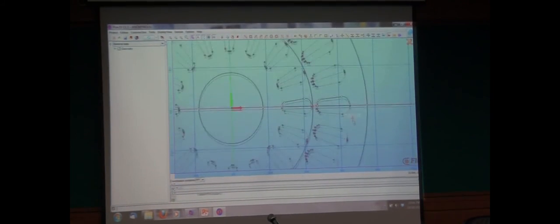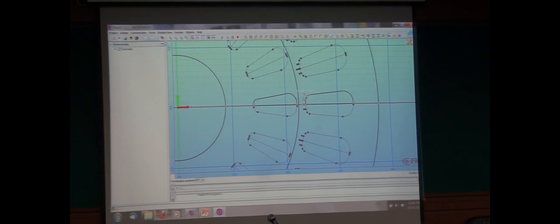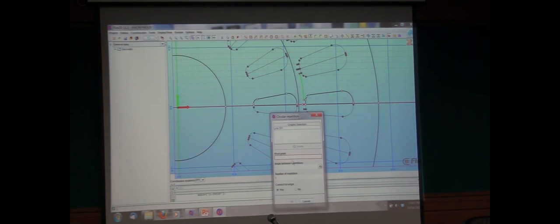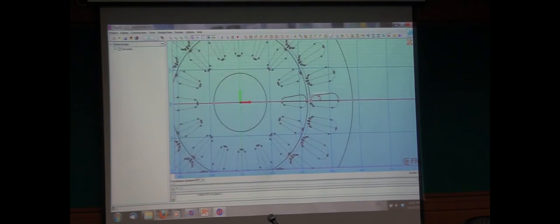And now the only thing that I would have to do is actually close this slot, which I haven't done. And that's actually done with the arc circles, where I'm going to come from here, and then I go from this point to this point. And now this line, again, I can actually duplicate it as I duplicated before. The pivot point is still the same, right here. And the angle is 15, and I need to do it 23 times. Okay, and my geometry is all set.